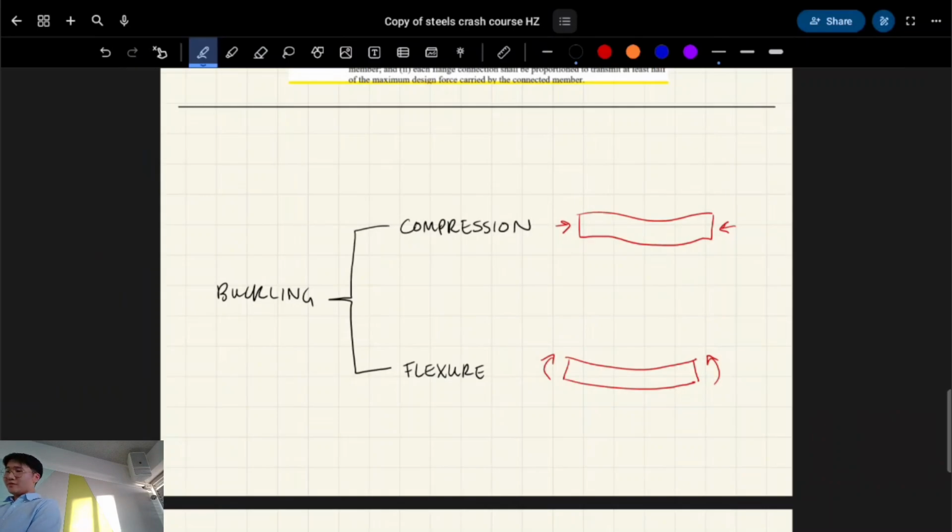Is it going to perfectly squish up, essentially, based on this shape? What's going to happen to it? Is there going to be any like eccentricities? Right? Yeah? So why is that? So our column is going to buckle. So buckling is where it goes off its center as you squish down on it, right? That's the general concept. Okay?